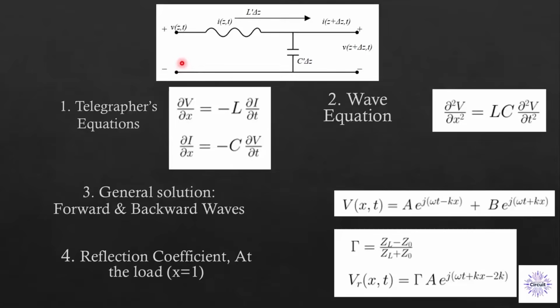As you know, when the frequency is high, if you want to look at the voltages as waves, the wavelength of the voltage becomes small, meaning that in a very short distance, the wave may cycle through its entire period. So the voltage may change in a very short distance.